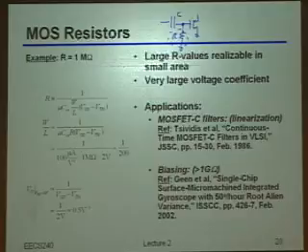Okay, so you said nothing if the gate current is 0. So, is the gate current 0? Okay, so you said it should be, and somebody else said it's small. So now let's be really precise and actually specific. I'll give you guys a hint. In a 90 nanometer CMOS technology, that gate oxide thickness is somewhere on the order of a nanometer. So is the gate current precisely 0?